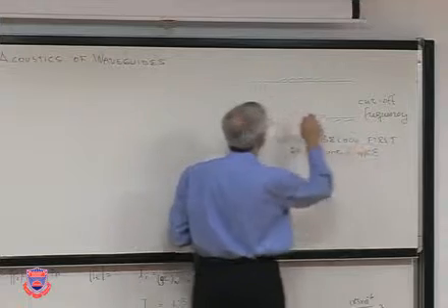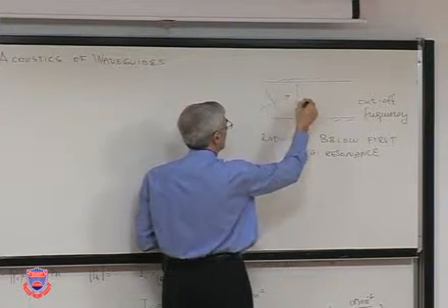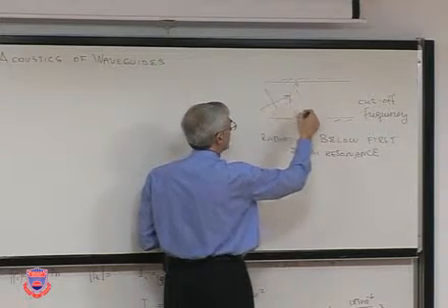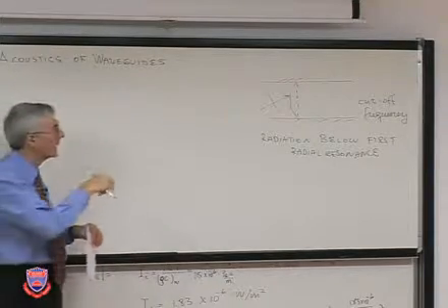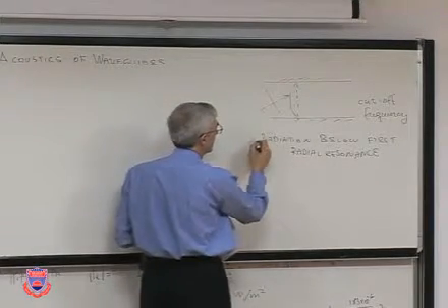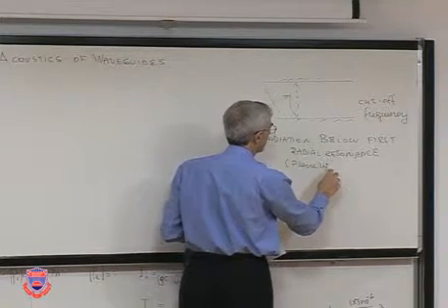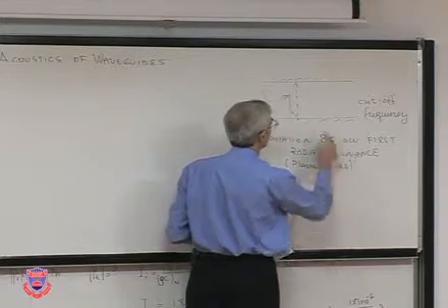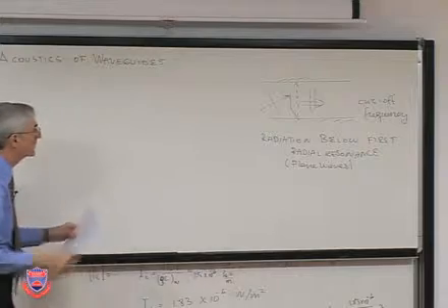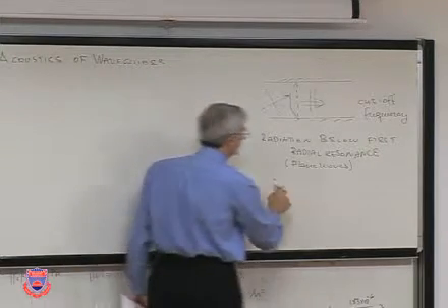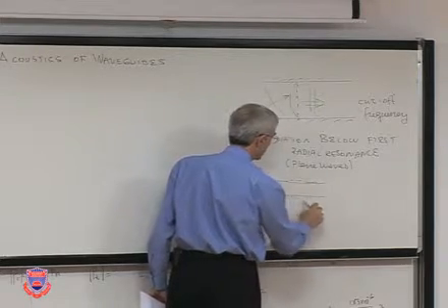Again, what that means is this is the radial direction, okay, and the first resonance here is the cutoff frequency for that mode, and below first radial resonance, it's all plane waves, just like we have seen before. Sound will be radiating straight down. Well, what happens then if you have a pipe that's flexible?